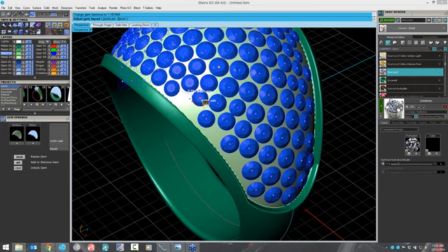If I need a new gem in here, then I will click the Alt key. So I hold down Alt, click on here, and it adds a gem. I can then immediately hold down Shift and scale that gem, and then click in the center and move it. If one of the gems is placed and gets locked, okay, you can hold down Control and still move a locked gem.